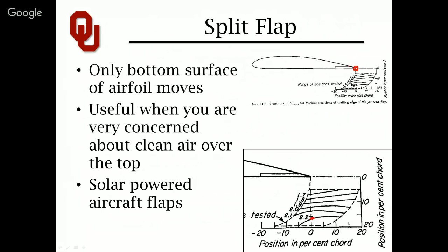It's a no-brainer there. But it's also more difficult if all of a sudden you say, okay, I need to chop off the trailing edge and put in control surfaces now. The design crew looks at you very angrily and says, no, you're not chopping through our solar cells. Figure out a different way to do it. So split flaps step in and become employed in solar-powered vehicles.